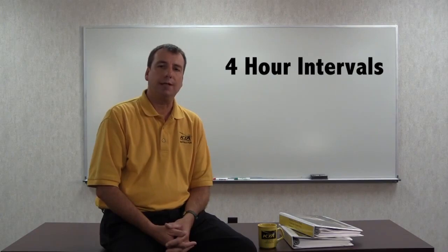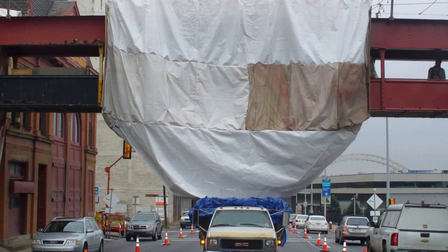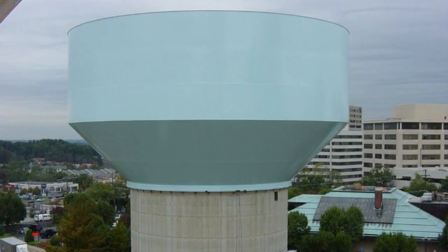Ambient conditions should be measured and recorded prior to startup of operations and at 4-hour intervals thereafter, unless conditions appear to be changing. In this case, more frequent checks may be required. If work will be done inside a facility, tank, or inside of a containment structure, then the prevailing ambient conditions inside of these areas should be assessed. That is, you are measuring the prevailing ambient conditions where the work is being performed, not necessarily the weather conditions. For example, when working inside a tank located out of doors, the conditions along the floor will be different than at the roof.